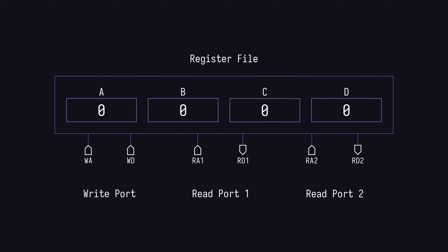If you recall the register chips that we've used in the processor so far, in the program counter, for example, you'll notice that each chip has its own data input and output ports. So basically, we could just place, say, 10 of these register chips onto a breadboard for 10 registers for our CPU, and then have 10 data input ports and 10 data output ports right there by just hooking up directly to these chips. But those 20 ports result in a lot of unnecessary wires, and we'd be able to write and read all registers at once.